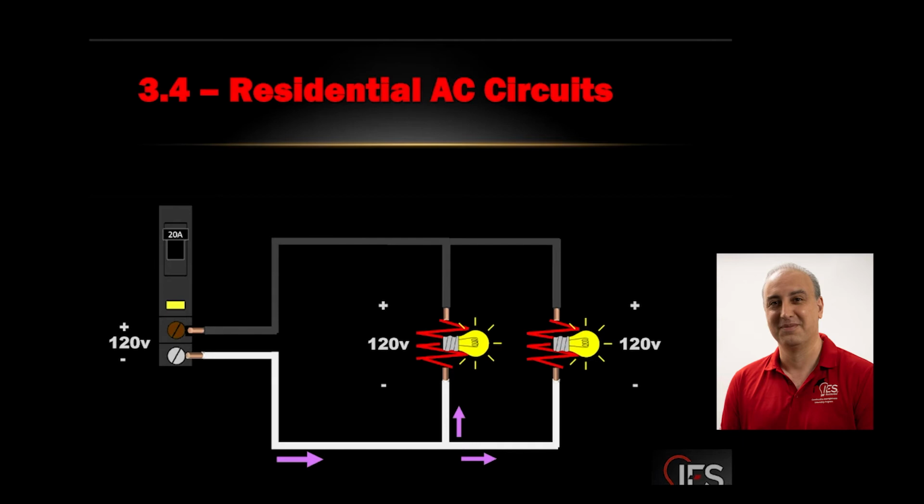System voltage in our residential is usually 120, 240 in single family. In multifamily, we usually have multiples. You have 120, 240 for standard stuff. Then you might get a 120, 208 or 277, 480. There are different systems if the three-phase comes in. But when we say system, it's because the voltage in our design is supposed to stay the same. We're not supposed to change the voltage.